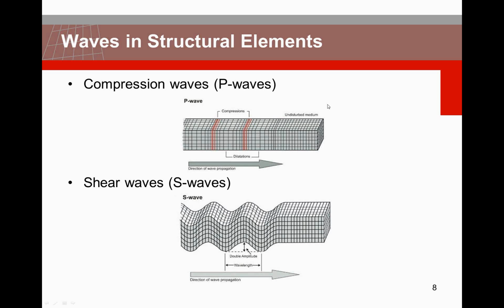What kind of waves do we have? We have compression waves, which will occur both in solids and in fluids. And there you see there is a sort of compaction in these regions. So this travels on. It's dilatating your soil, your medium, or your fluid. Then another one is shear waves. Shear waves are not occurring in fluids. They're only occurring in, say, solid kind of materials.